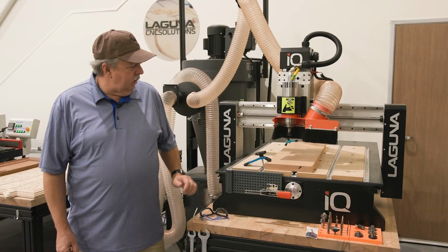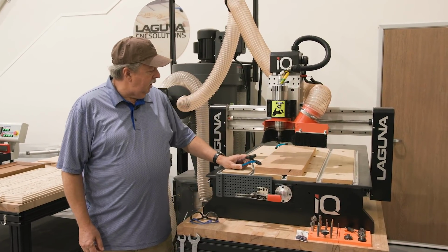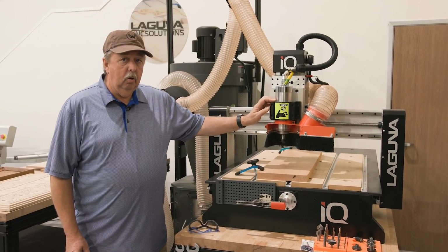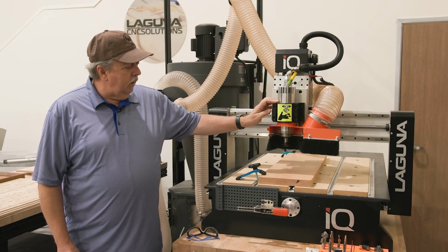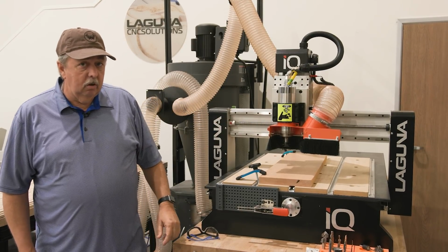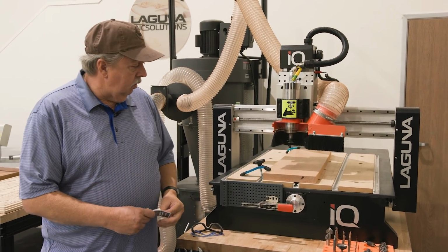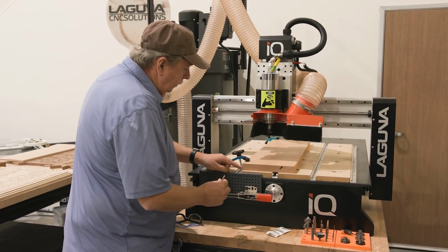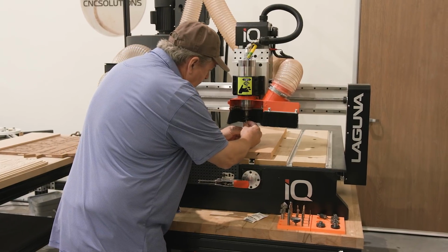Okay, we've already done a couple things in setting up to carve this material. We've fastened it down. We've made sure that the machine was turned on and homed. Remember, we home the machine every time when we start this. We're at the point now where we're actually going to install the bit and get ready to cut this thing. So that means we have to install the bit, and then we'll have to set the XY 0 axis.